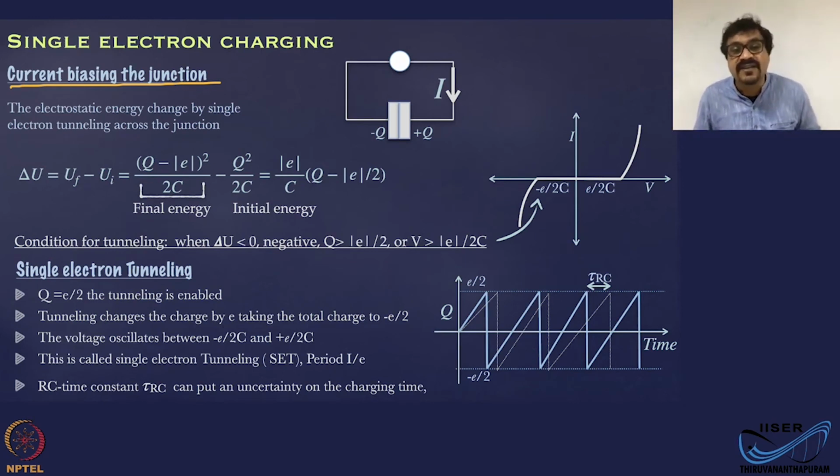One of the practical ways to make a current source from a voltage source is you just attach a very large resistor in series with the voltage source, then it becomes a current source. Because then the resistor which is in series is going to decide the current. That is going to dominate the whole transport. But of course, you have to make sure that the value of the resistance is really large compared to other resistive elements in the circuit. Then only that's going to dominate the transport. All right. So for this discussion, let's assume that you have a current source driving a current through this system.